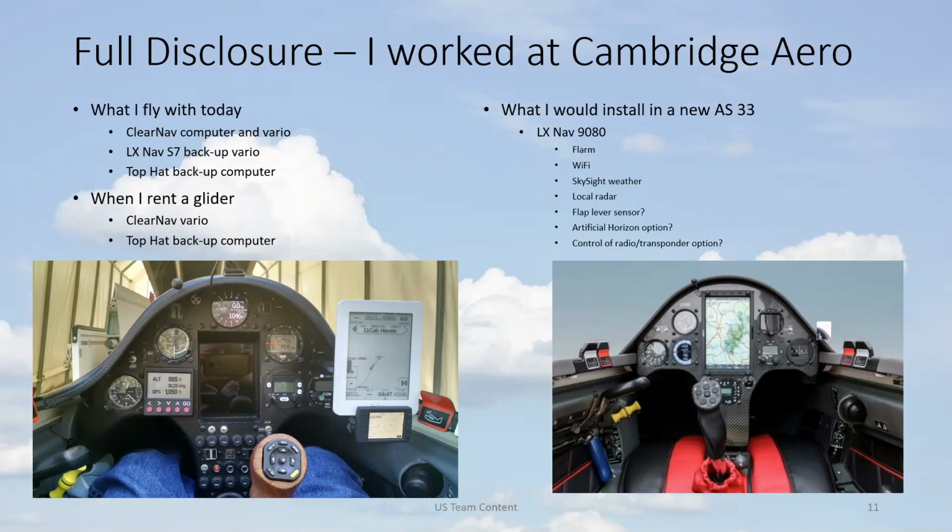Yeah, the second observation I had is fairly simple, but it's important. If you're using two batteries and you're changing in flight between the two batteries, it's very important to have a system that allows you to go from battery A to battery A and B, and then battery B. If you use a rotary switch, none of these computers will tolerate even a microsecond of being non-powered. And they all crash if you use a rotary switch. Yeah, that's a great point, Roy.